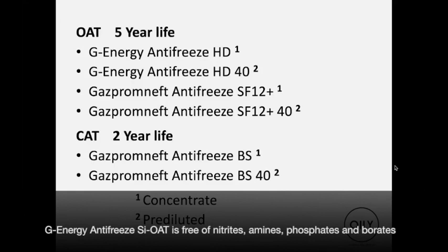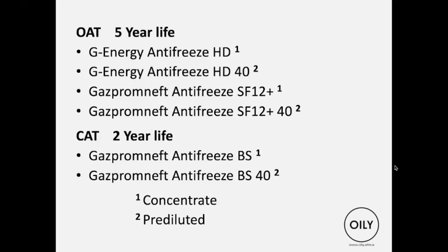Yeah, that would be for passenger car. But it meets all the Mercedes, Cummins. Mind you, Cummins have got 27 different antifreezes. Only, yeah? Only. And many of those are incompatible with each other. They will cause engine failure if you mix them.